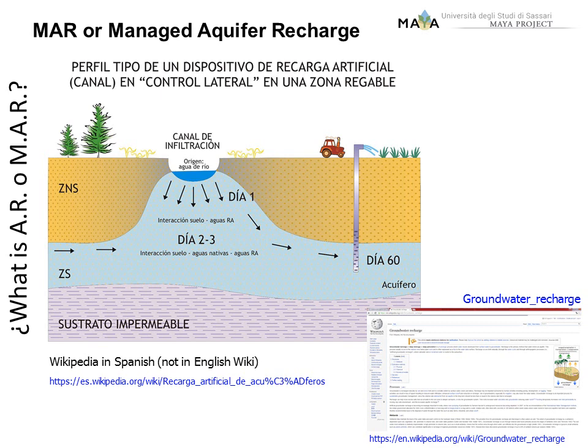The idea is quite simple. We introduce water either in a point, a line, or a polygon. This water progresses across the unsaturated zone until it reaches the groundwater level, and this water already stored is extracted whenever necessary, either from the same point or from another well or borehole or whatever.